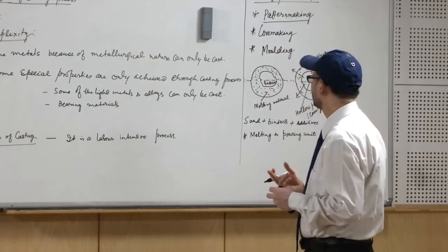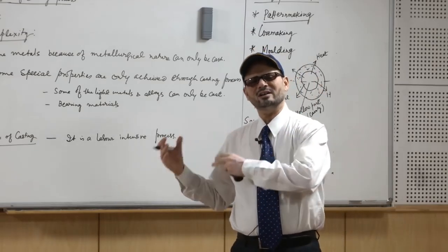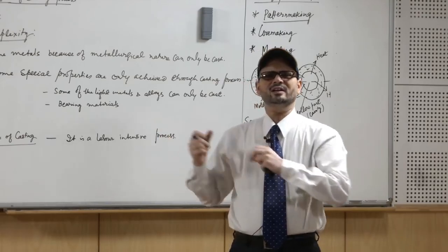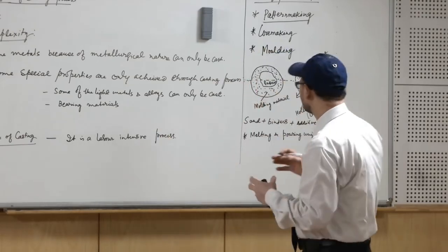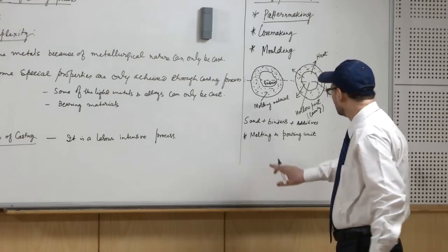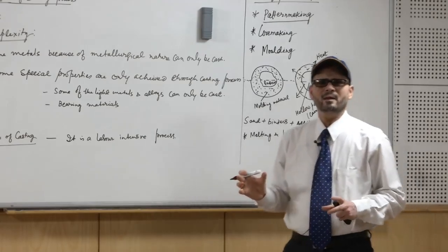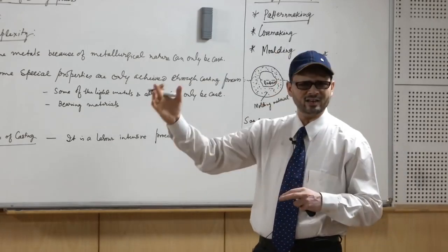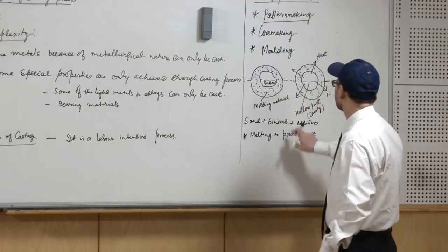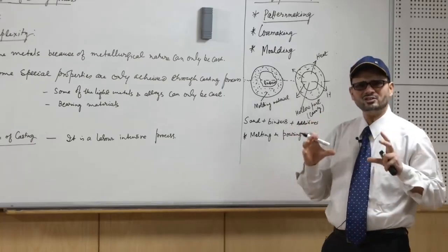So, you may have the furnaces like cupola furnace for cast iron, you may have the arc furnace, you may have the induction furnace. So, all these furnaces are placed in the melting unit. From there you will have to transport these metals through cranes or by other means, and then you have to bring it to the place where you have to cast it.